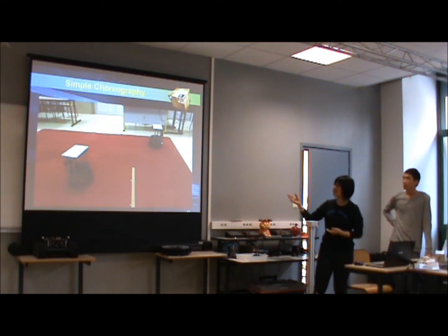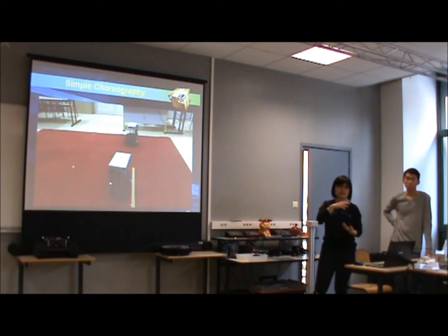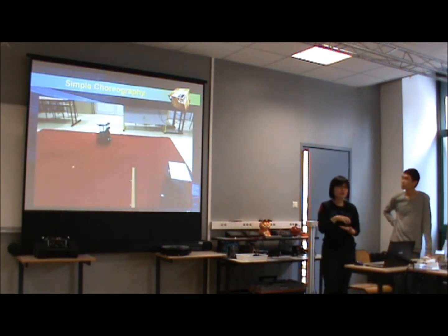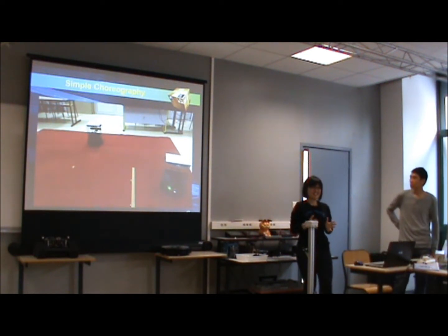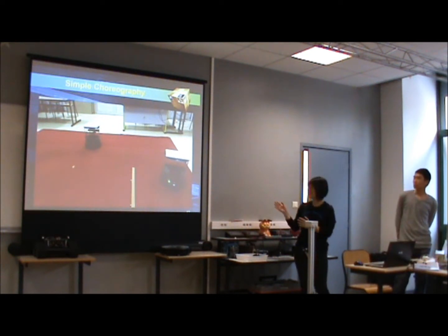And actually for this demonstration, I'm using the already embedded Python program for moving a square. In the program itself, it states that it's going to move 90 degrees. But then I have to change some of the measurements to 87, and only then does it move nicely 90 degrees. Otherwise, it's going to move more than that.